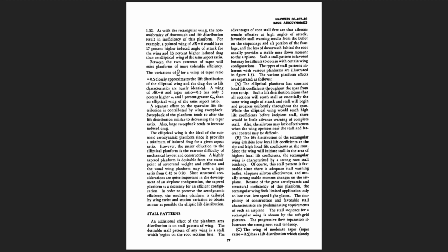Stall patterns. An additional effect of the planform area distribution is on the stall pattern of the wing. The desirable stall pattern of any wing is a stall which begins on the root sections first. The advantages of root stall first are that ailerons remain effective at high angles of attack, favorable stall warning results from the buffet on the empennage and aft portion of the fuselage, and the loss of downwash behind the root